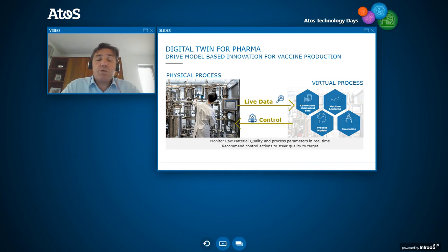So we are measuring in two ways. First of all, the DLS as a PAT sensor to predict the particle size. And secondly, the model, which is also predicting the particle size of our critical quality attributes. And in this way, we have a kind of backup system, one with the other.